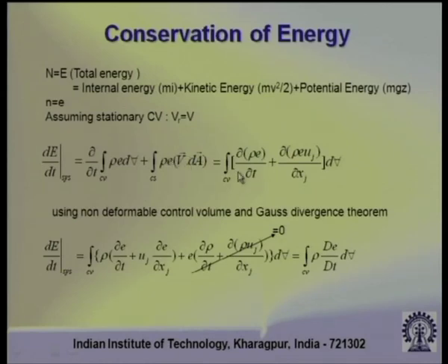We can make further simplifications to this term. For the first term, we put the time derivative inside the integral by considering a non-deformable control volume. Then the second thing we do is write this area integral in terms of a volume integral using the divergence theorem.